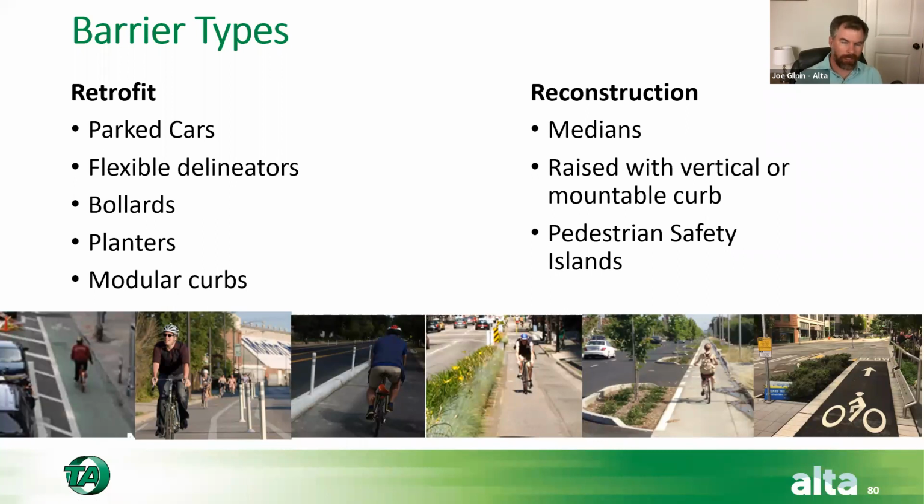And the city's saying we can't put trees in the buffer, even though we've got 6 feet of buffer, because it's within their 7-foot clear zone. And this is on a 20-mile-an-hour roadway. That's that city, so I can't get too far into that beyond that. So it's approachable. I don't believe that the crash data supports significant problems with clear zones at low speeds.